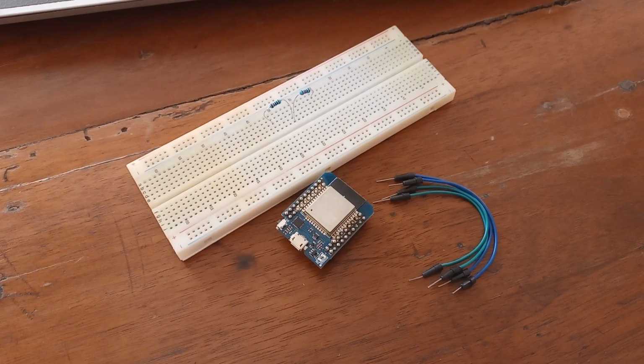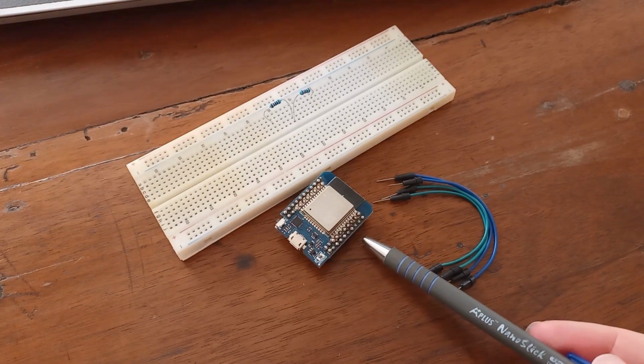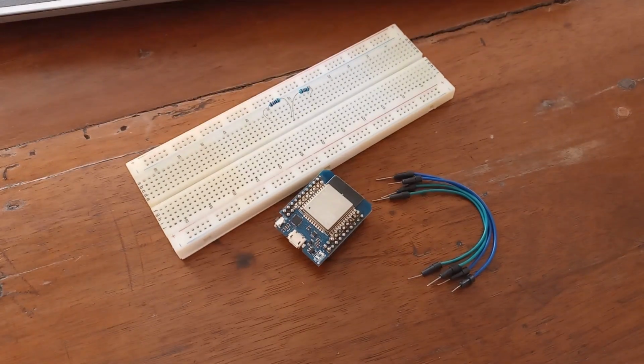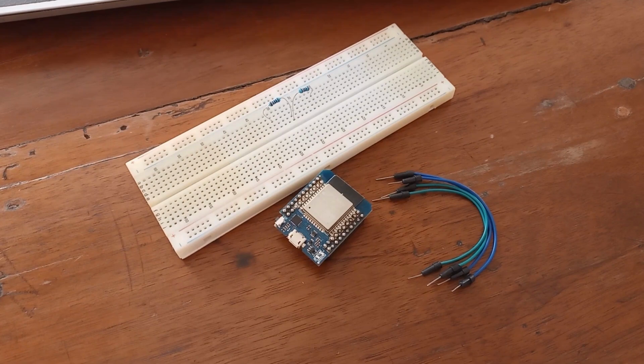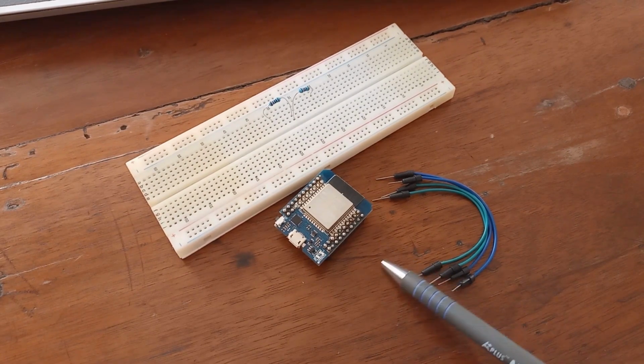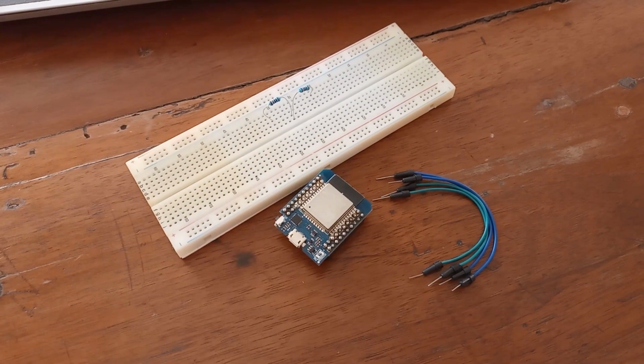So in today's episode we are going to talk about deep sleep mode with ESP32 microcontroller. And this feature you are not going to use too often except in cases when you need portable systems. So in cases when you have some regular power supply to attach to your microcontroller, you don't have to worry. But in situations when you have to use batteries with your microcontrollers, well, consumption is a serious problem. And how actually deep sleep mode solves all of that?